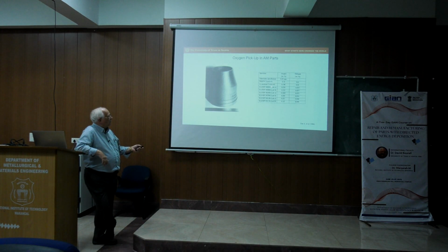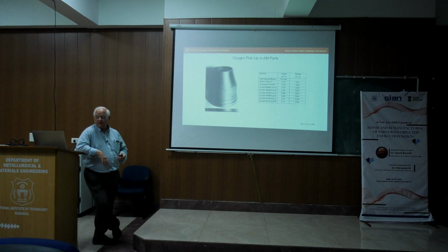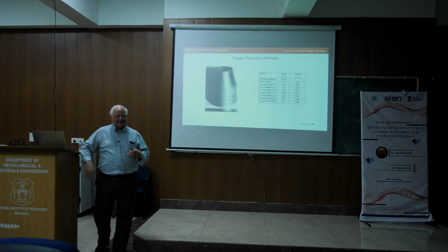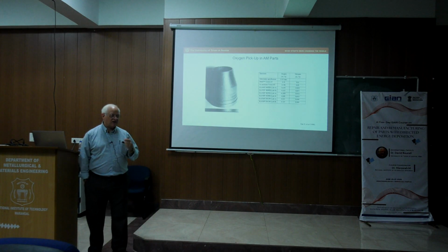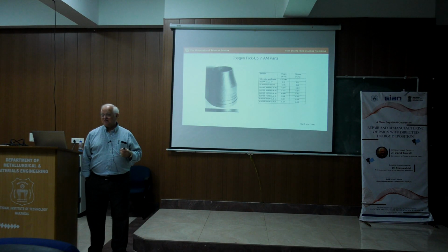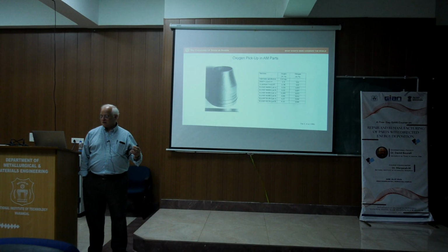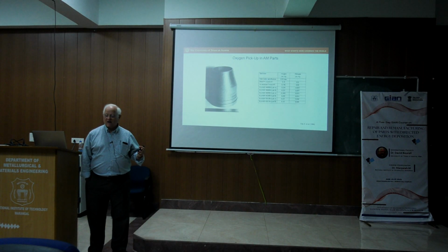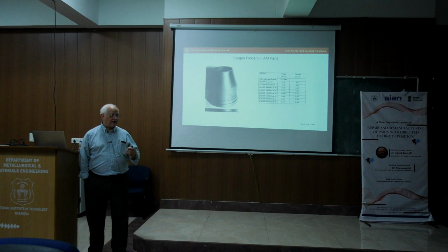What we see here is the Sidewinder specification was 0.25%. 0.25% oxygen was the maximum allowed, because I mentioned, I think yesterday, the problem with oxygen in titanium is it lowers the toughness. And again, the oxygen goes in substitutionally, so it's not present in the titanium as an oxide.